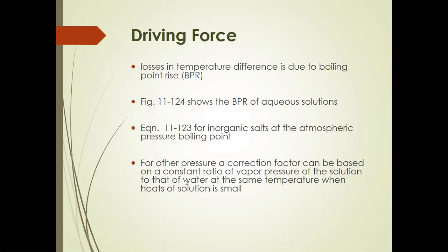So if the problem does not say that there has to be a correction factor, it's okay to assume that your boiling point is based on atmospheric pressure, or your evaporator is operated at atmospheric pressure.